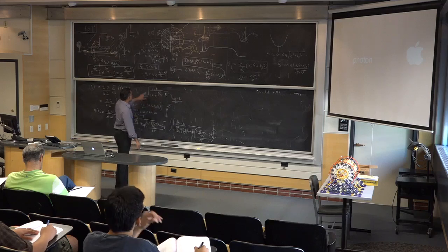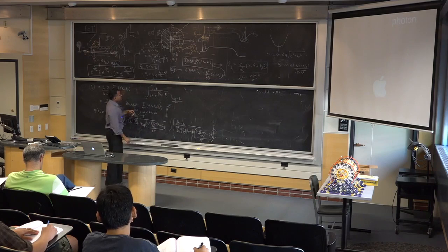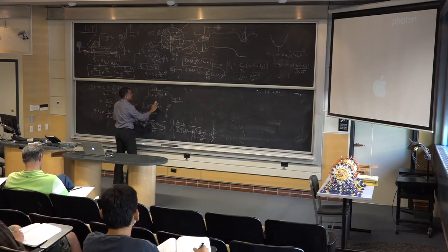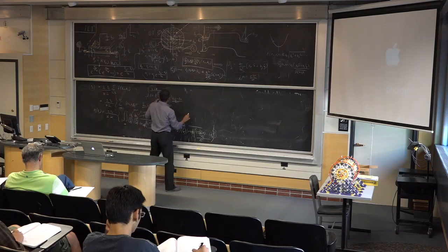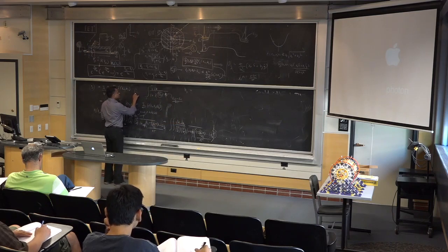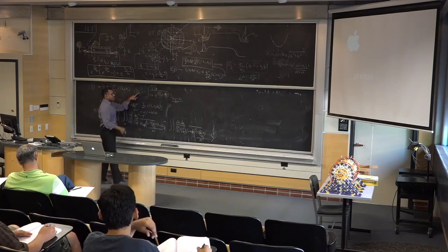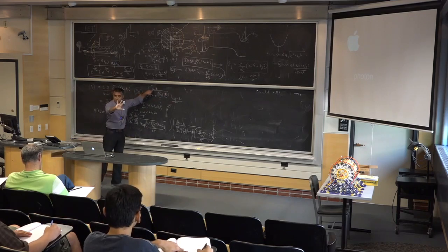Okay, and this integral goes from 0 to infinity. There's some stuff sitting in the front, and I think you know how to deal with this. You just substitute that as energy and all that. What it becomes is a Fermi-Dirac integral of 0th order. This is what you're going to get, a Fermi-Dirac integral of 0th order with the argument. This is the argument because k is integrated out. Once you integrate, k is gone, right?